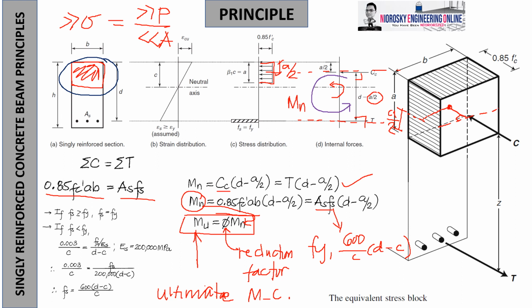So after that, usually, that is the topic, and then we compare it with the maximum moment of the beam, and then we can say if that is safe or unsafe. It is safe if the capacity is more than the actual, and said to be unsafe if the capacity is less than the actual. So therefore, there could be a redesign condition out of that.